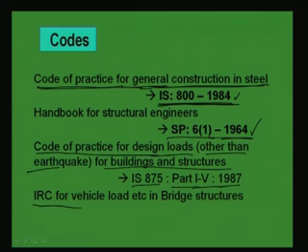Then the IRC code, the Indian Road Congress code, will be required for vehicle load calculation. This is mainly required for bridge structures. Sometimes when we go for gantry girder design, the moving load comes into the picture. So there we may need this code, these codal references.